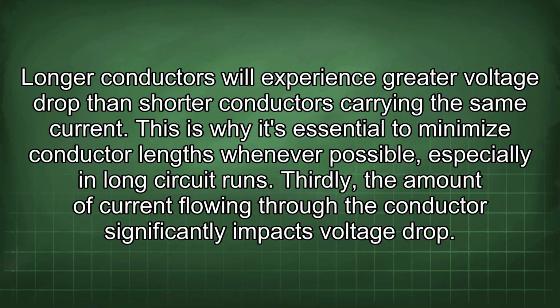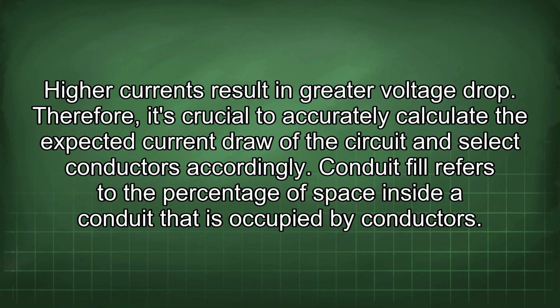Thirdly, the amount of current flowing through the conductor significantly impacts voltage drop. Higher currents result in greater voltage drop. Therefore, it's crucial to accurately calculate the expected current draw of the circuit and select conductors accordingly.